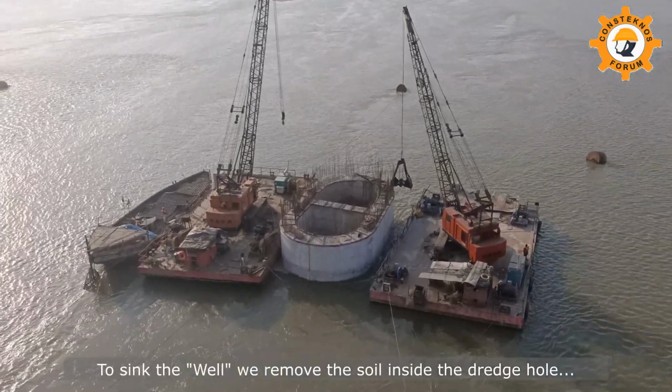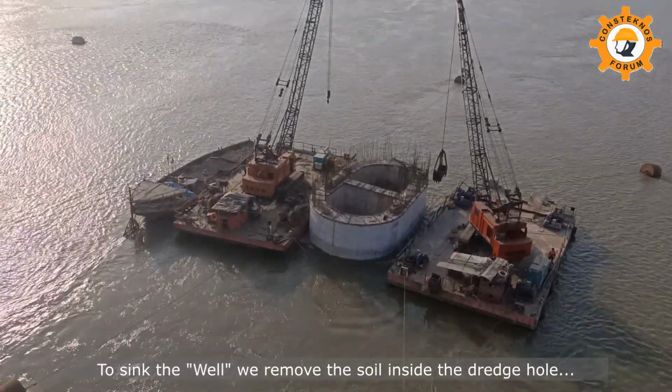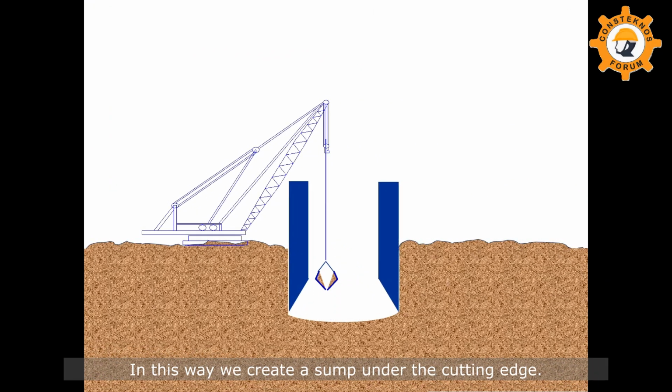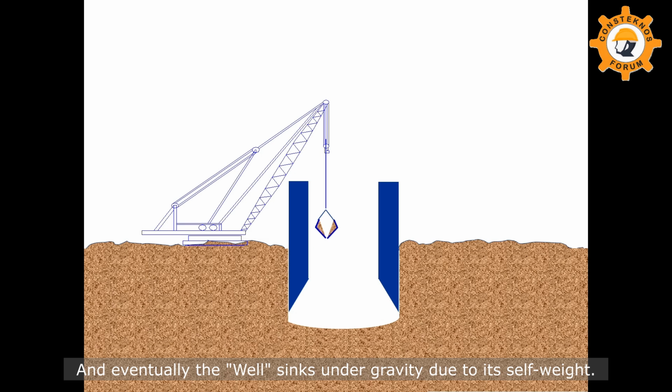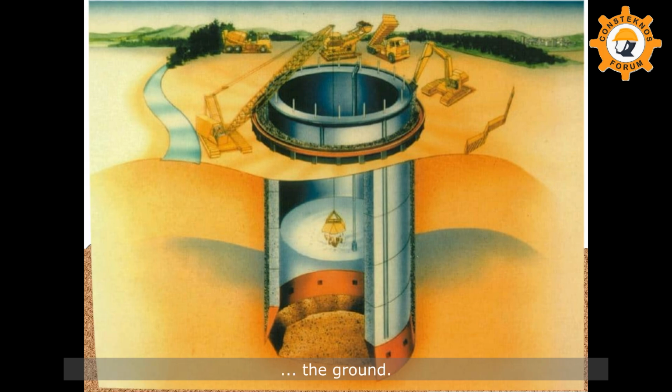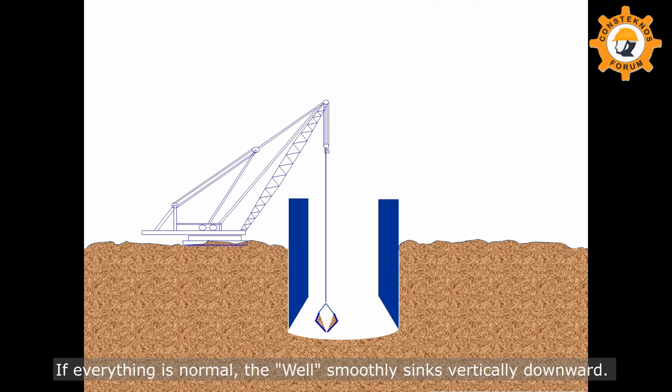To sink the well, we remove the soil inside the dredge hole from the bottom of the well. In this way, we create a sump under the cutting edge, and eventually the well sinks under gravity due to its self-weight. When the well sinks by self-weight, the soil inside the shaft is dredged by suitable means, which aids further sinking into the ground. If everything is normal, the well smoothly sinks vertically downward.